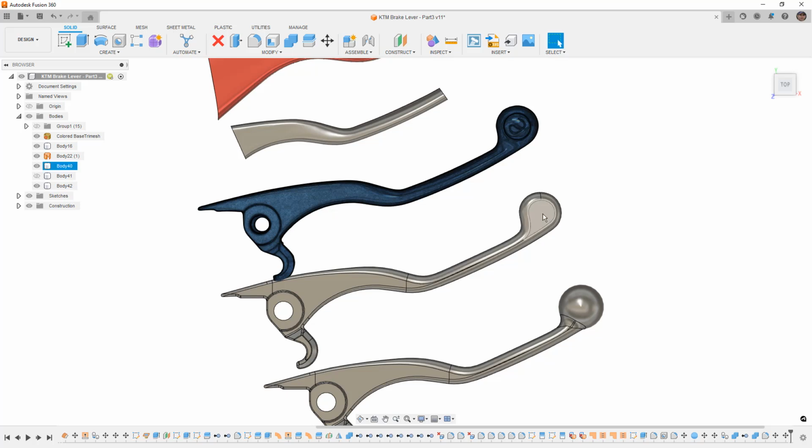But I think overall, either of these two final designs here are going to be a good way forward. I could likely 3D print and test these on the bike, not test them like ride it, but test the fitment, make sure that everything fits and works, and then commit to CNC machining a version of this. This also gives us the flexibility to make some design changes.